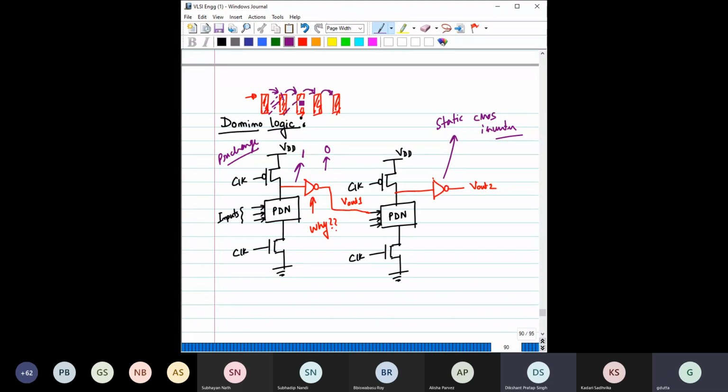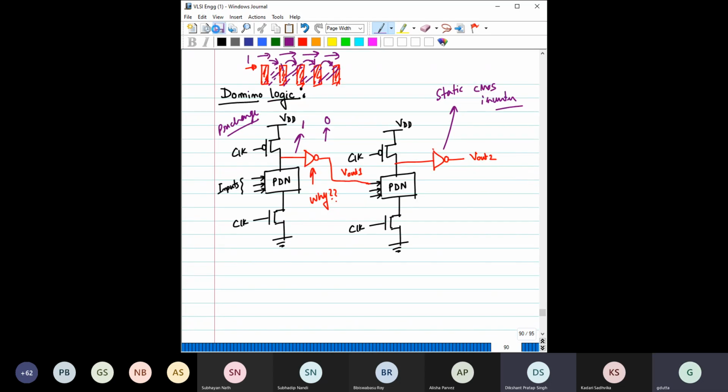It keeps on going like this: this will fall on this, now this will fall on this. So you give a push here, this gives a push here, and it transfers one after another. We'll see a similarity here, because once you make a change, that change will propagate one after another. That is why this logic is called domino logic. Let us see how this is happening.